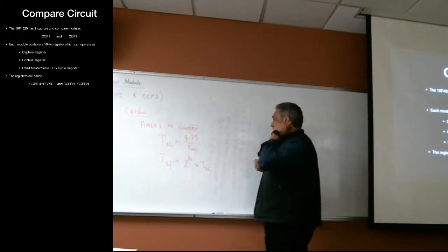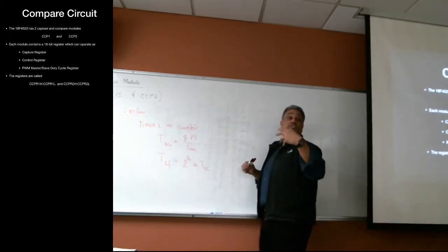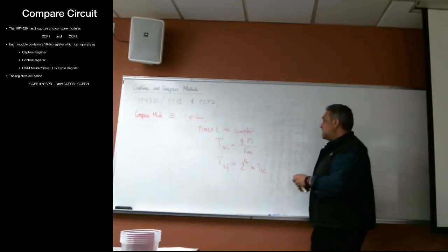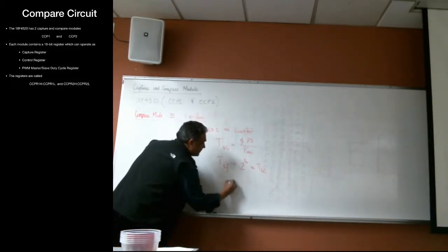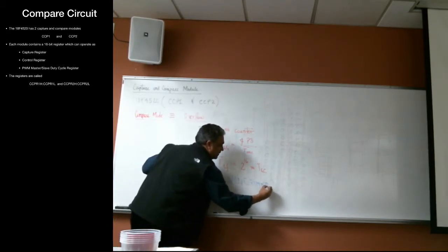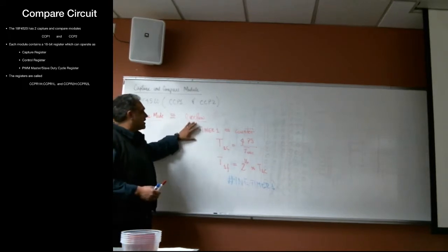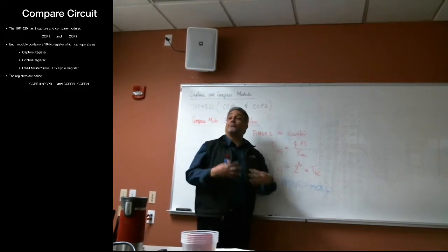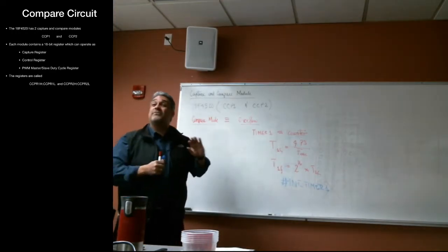And this moment of overflow is the moment in time where the timer cannot count anymore. And then the count is going to go from its largest number back to 0, and it will begin the count again. And we said that that circuit could be connected to an interrupt vector that was called #int timer 1. All right? So there the system is set. And so we have a circuit in overflow that has the ability to interrupt the microprocessor in predetermined periods. Right? That was the idea behind it. And so you can do all kinds of pretty fun applications with this.